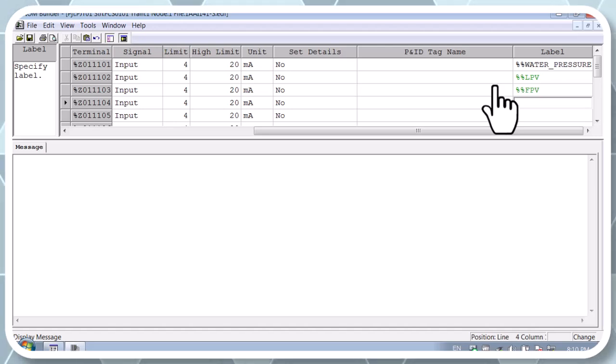When we use the double person symbol, it means that we register the name in the input output model. When we use the single person symbol, we are referring to the registered plant tag. And sometimes we use it without the person sign, and in that case we are using the tag in the control logic, PID blocks and calculations.